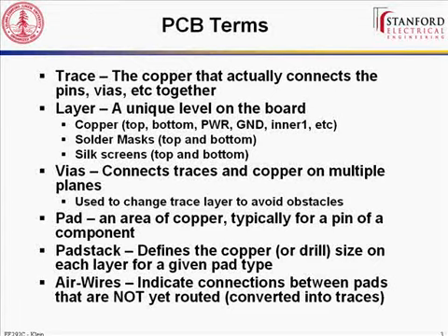So you can use these copper pours for various things. Under your LCD panel, for example, you'll see a very large square, or a rectangle, coming out, and that's using the copper actually as a heat sink for your voltage regulator coming off the tab. And then throughout the rest of your board, we flooded a lot of the area with ground in between the traces, and that helps decrease your signal noise, which we'll talk about later on.